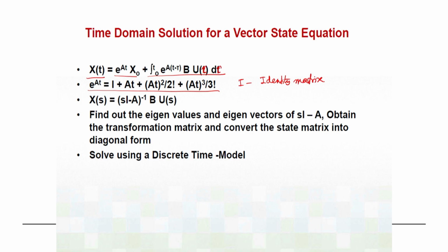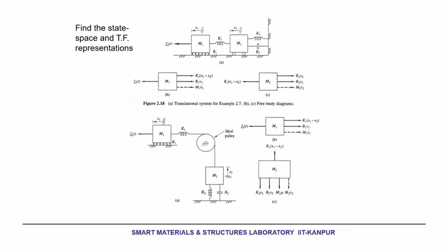Once I get this, I can of course write this equation in the Laplace transformation domain also. I can write it as X(s) equals (sI minus A) inverse B U(s), and that way I get a Laplace transformation and the corresponding transfer function of the system.